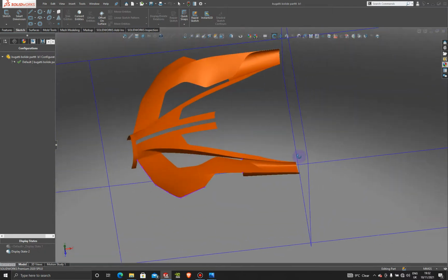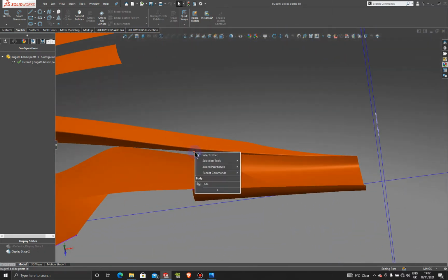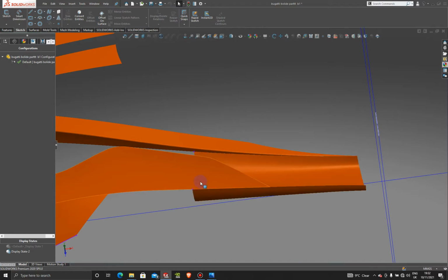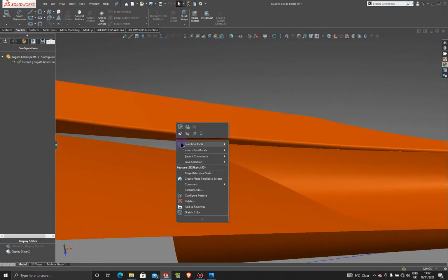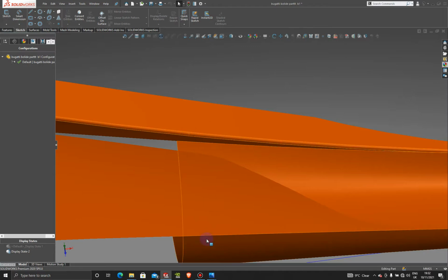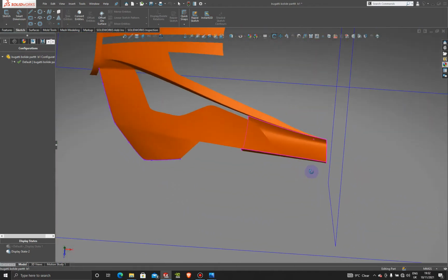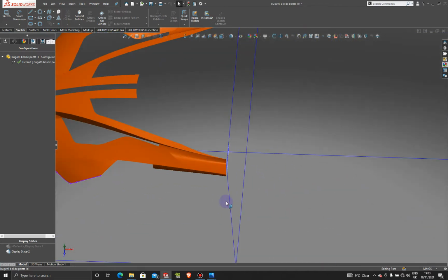First of all, we've got some points here we want to get rid of in our second display state. Oh, let's do a Control Z because that hit our surface there. So Control Z brings that back. Then let's come in here and make sure we own that point, and then hide that. It hides that one as well. So that's pretty good. All right, now we just need to create some scaffolding here.